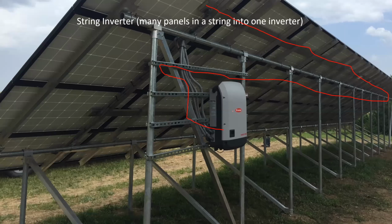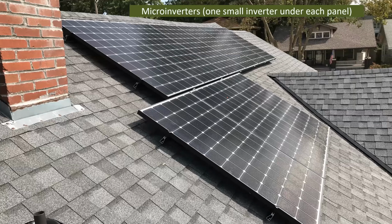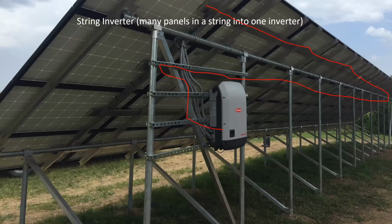String inverters tend to be the lowest cost, but because of the electric code, they tend to be mostly installed on ground mount systems. They also have some other advantages and disadvantages as well, but they are the lowest cost and work really well for ground mounted systems. If you're doing a ground mount, you really probably should be thinking about a string inverter.